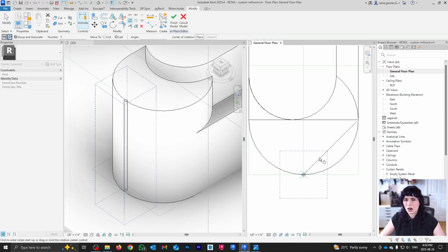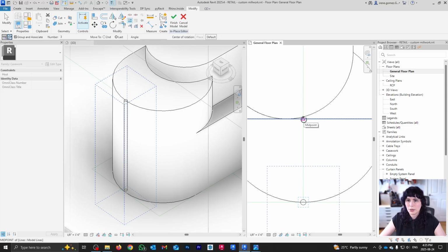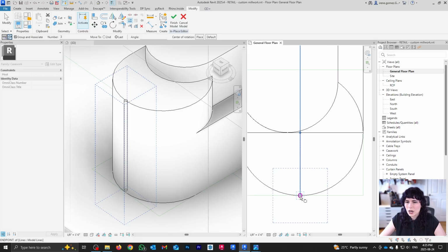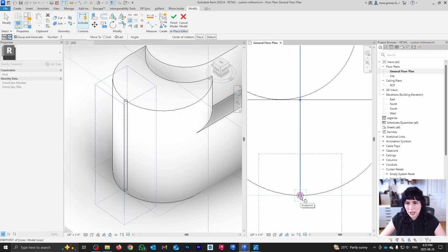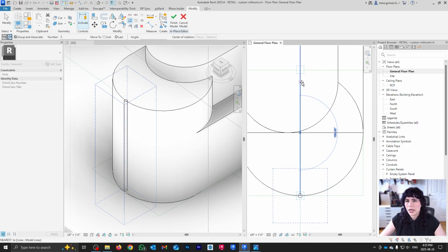So there you go, array, and we're going to say first and last, perfect. Placement of the center of my array is going to be here, perfect. And now I'm going to click here to pick it up where this first guy is, and bring it all the way here. You may be like, well, why don't you just put it there?